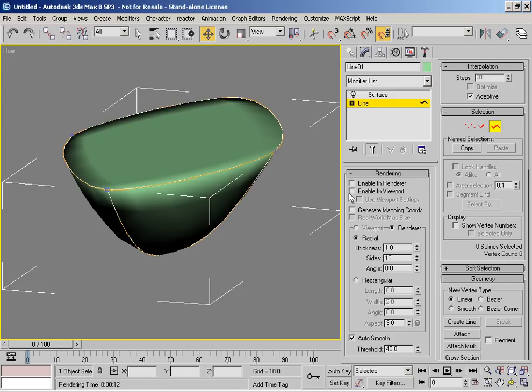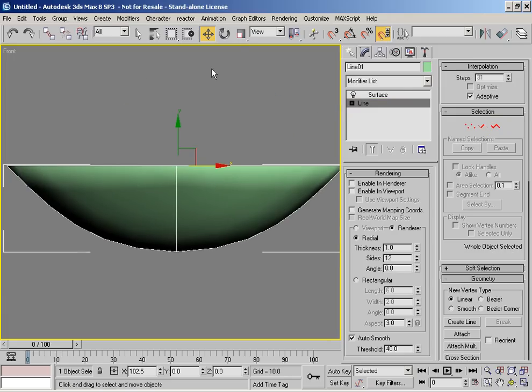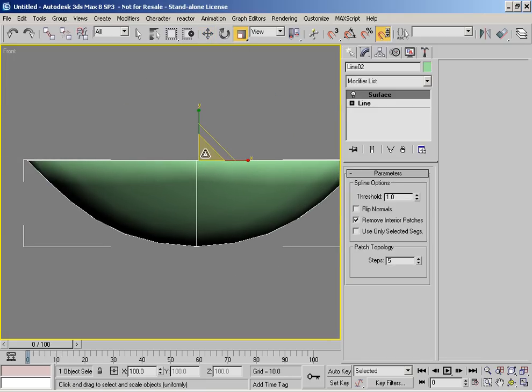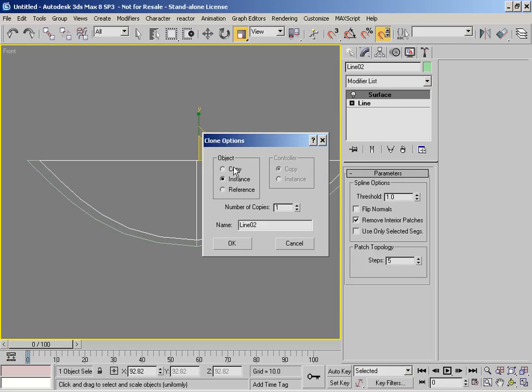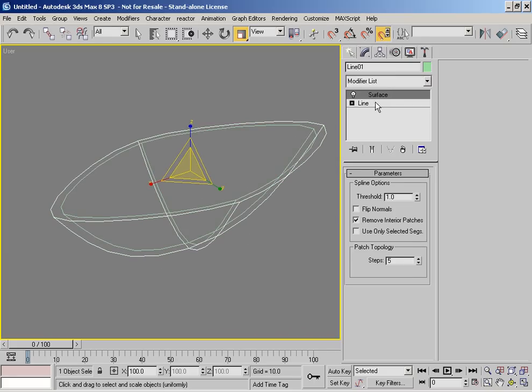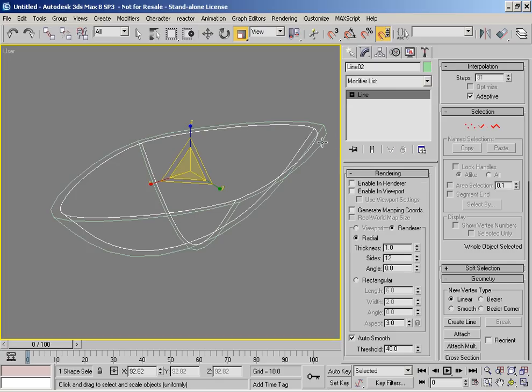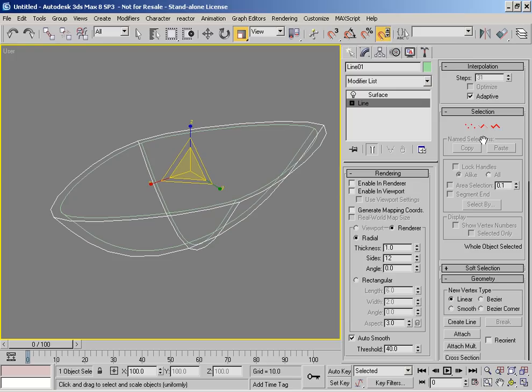and then what I want to do is literally scale the boat, create an exact copy of it but a scaled version of it, just like that. So I'm just going to do a copy, select the original one, actually go to the other one, ditch that surface because otherwise I won't be able to merge it because it'll think it's geometry. Go back to the line, then I want to attach this set of splines to it.